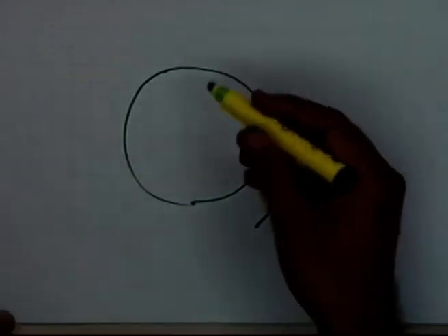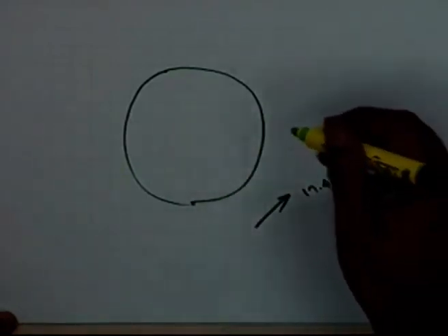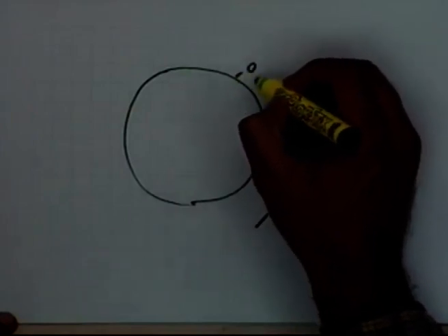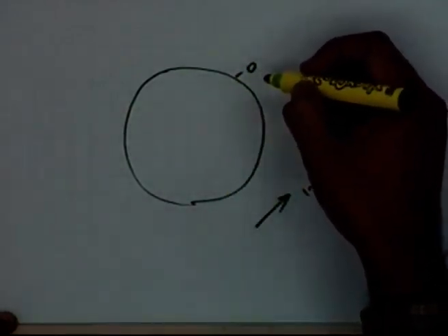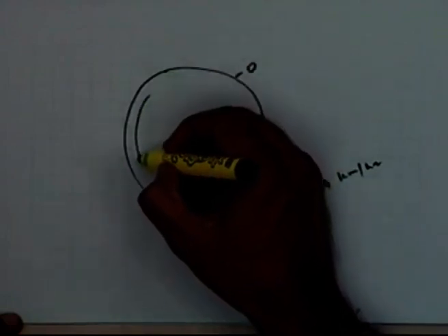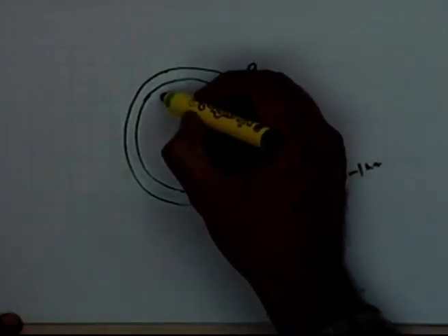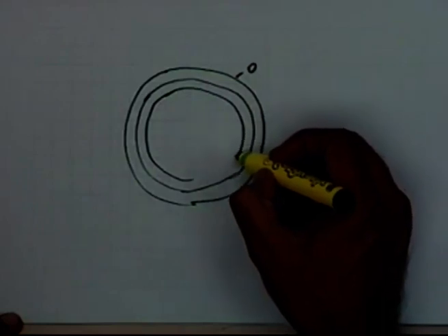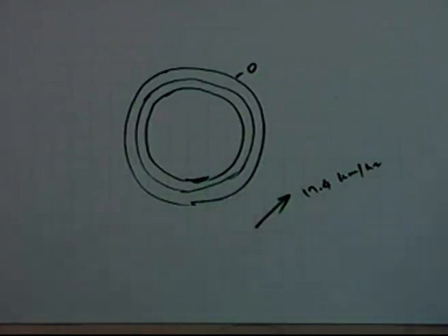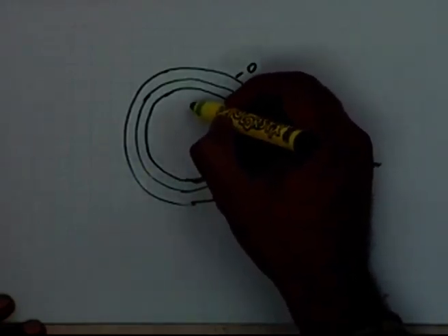So in this case, because of this wind which is prevailing at that particular site during the period when the sprinkler was on, you will find that if this is zero depth, there might not be much difference in the pattern where the depths are low, which are the side segments, but the difference will be quite excessive when you come to the central portion.